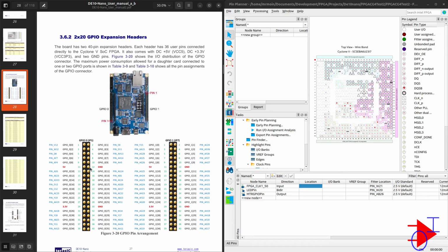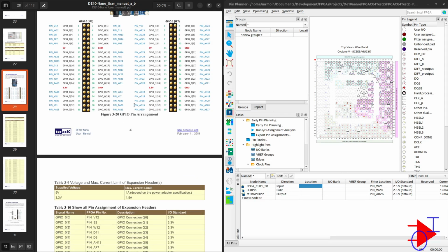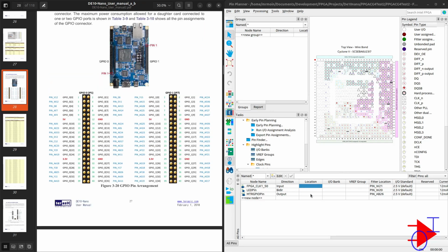Pin 10 and pin 12 is what I'm going to choose. Pin 10 will be our motor output pin, and the ground will be the ground. And okay, so that's our motor pin. So let's do that. Location, and what you do is basically just write this notation, AH3.